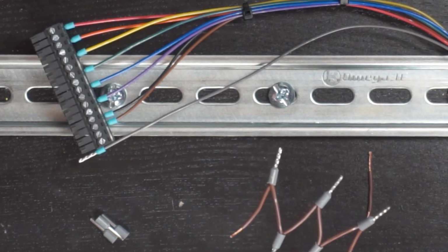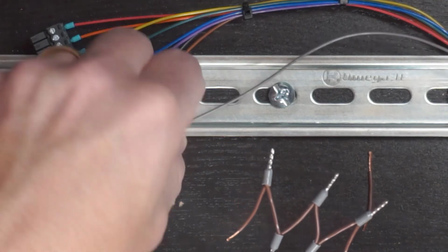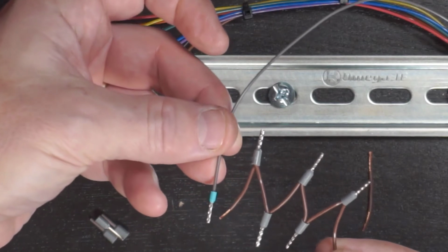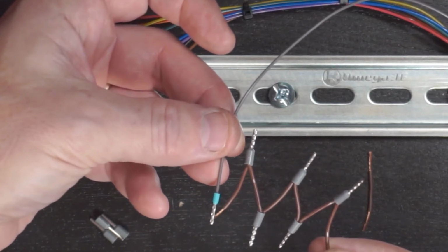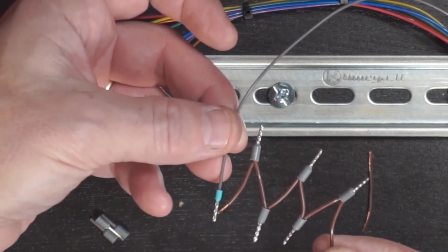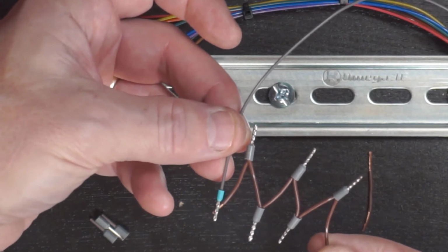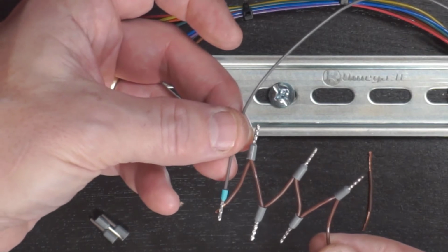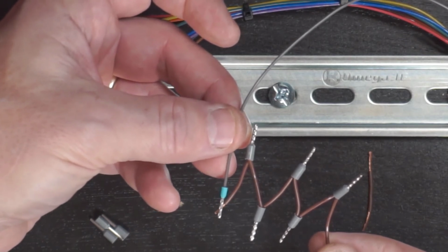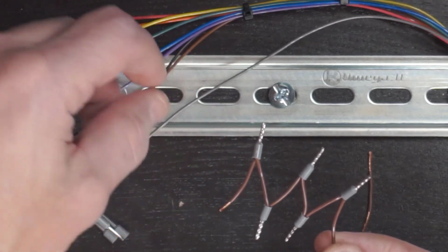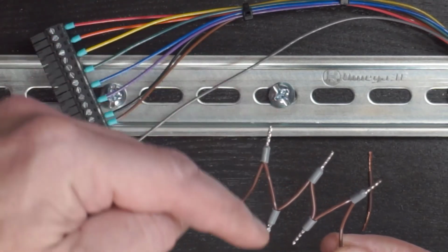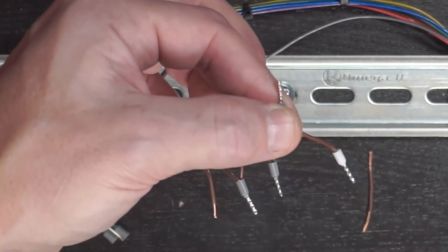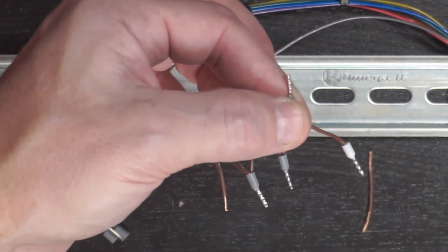What we're going to do here is this gray wire is where the V plus signal, the 24 volts, is coming in from the simulator. We're going to cut this ferrule off, put a new ferrule on with these two wires, and that'll be our first V plus connection that'll go into the common for relay 1. Then we'll be going into the common for relay 2, 3, 4, 5, and 6, and ultimately finishing up with just the single wire in the V plus terminal for the high-speed output. So that's what we're going to do.